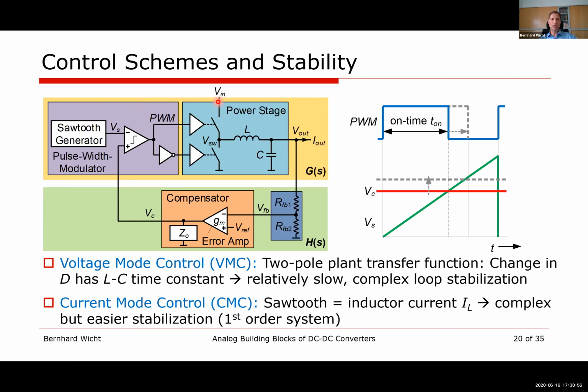In general, these switch mode circuits cause some EMC noise. Some comes from the parasitic inductance due to the dIdt transitions. The other component comes simply from the switch mode pattern, right? We get a rectangle here, and that's sending broadband noise.